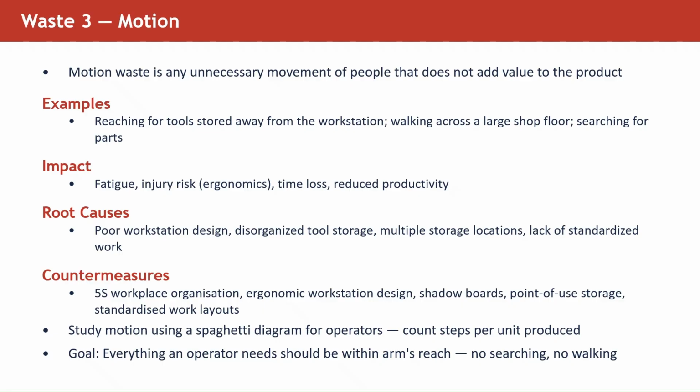Then the ergonomic workstation design, as we discussed earlier. Then put in point of use storage, and keep standardized work layouts which are visible. Everything that an operator needs should be within arm's reach. No searching, no walking, no stretching. We have to do the motion study before analyzing the work layouts. Keep everything nearby so that the operator won't get fatigued, and we will have the required production levels.